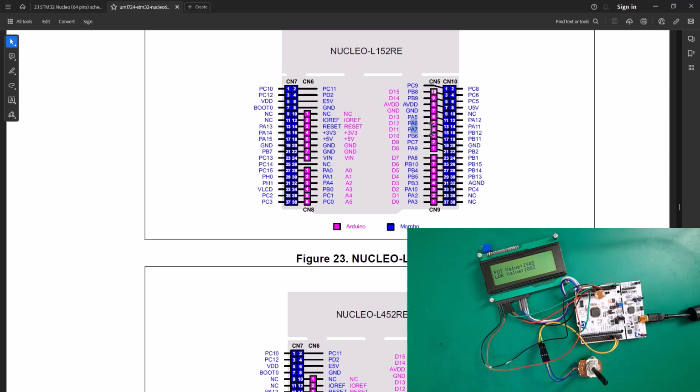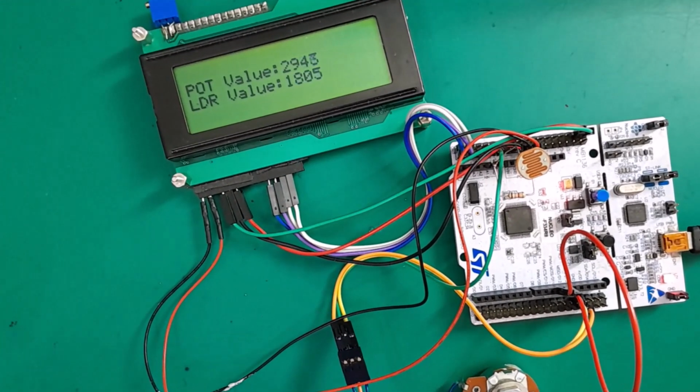It is connected on D11 and D12. So we basically need to put a jumper wire on D11 and D12 so that we can complete the loop test, right? So I'm going to connect 1, 2, 3, 4 here. So that will be D11, and right there will be D12, just like that. So that basically completes the loop connection.